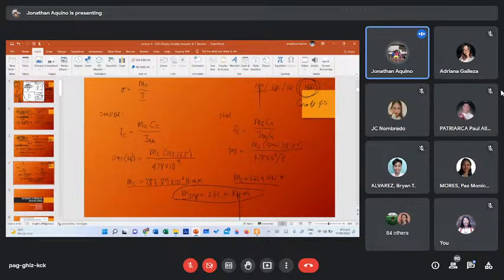So in a good design, the steel needs to fail first before the concrete. As you will recall from your testing of materials, when you test steel, you will notice the steel elongates but does not snap yet. Only after it reaches the required elongation does it break. In analogy to the building, you will see in your beam, prior to complete collapse of the structure, the concrete at the bottom will crack first. That means our reinforcement has yielded. So there is still time for the occupants of the building to go out safely.